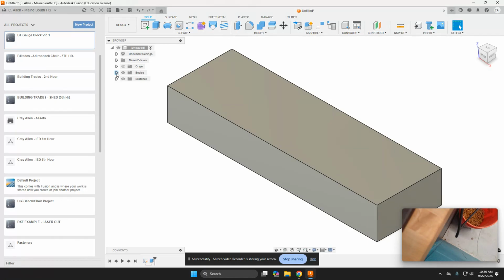So when we want to change geometry sizes or even the model size, this is the model, and you have a timeline down here. The timeline shows what you did at the very beginning, which is a sketch first. Then after we got that constrained geometry, which was black, we added that modeling piece, the 3D part of it. Again, Fusion is a 3D parametric modeling software, and you have to have 2D before you model it.